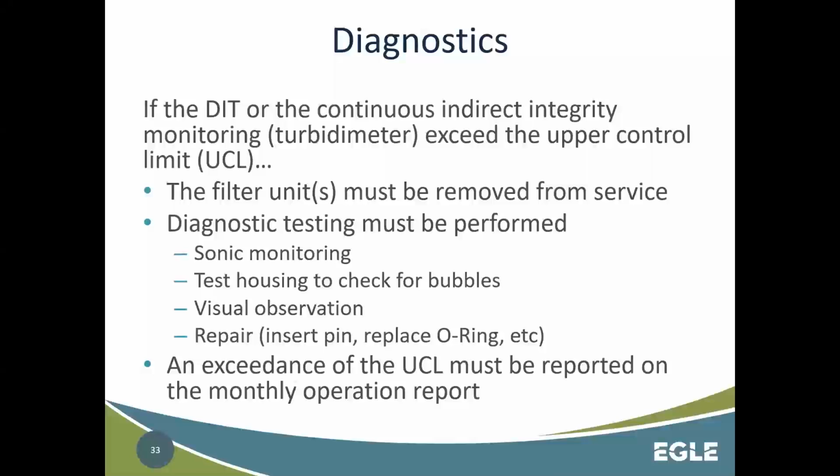Somebody demonstrated it for me once. You put the earpieces in and it sounds exactly like you would guess. You hear air bubbles in there. That's an indication that you've got a breach. They'll put it in a sonic testing mode, so it'll put air to the membranes, and then you just listen, and if you're hearing bubbling, then that's a problem.